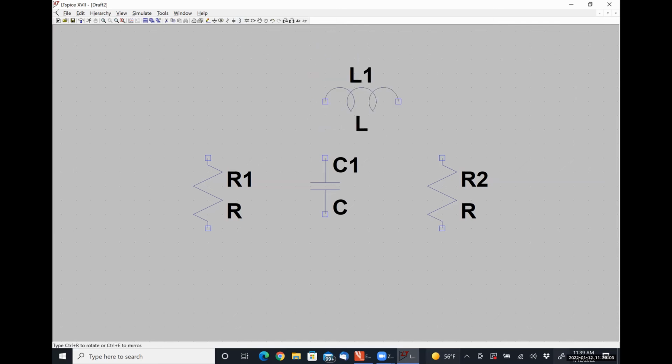All right, so when I simulate these circuits, I'm simulating the circuit during the transient condition. That allows me to not have to worry about setting up switches and making sure they're behaving correctly. It does force me to give my capacitors an initial voltage and my inductors an initial current. So during the transient condition, our circuit looks like this. We have two resistors, a capacitor here in the middle, an inductor like so. And let me wire this guy up.